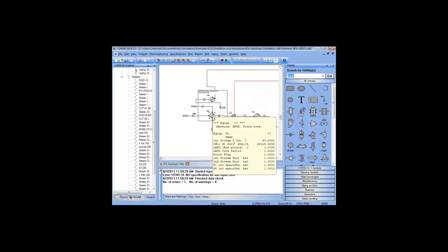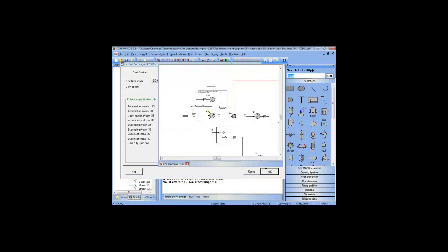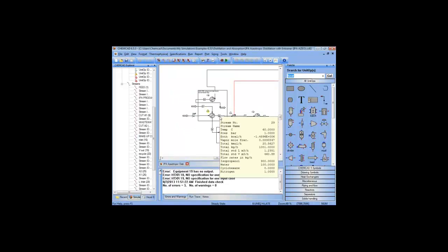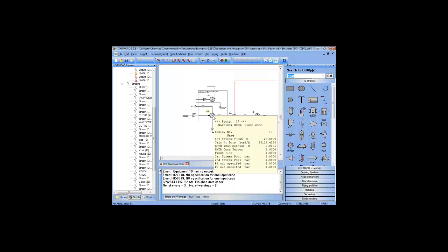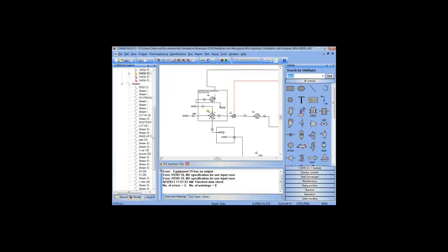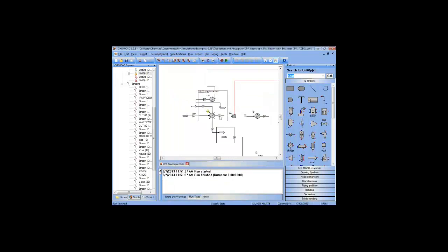And then I can just make adjustments and say, okay, maybe I can raise the temperature to 25 degrees. Do I have enough heat to do that? Right, so I'm still, well, I don't think I actually ran the simulation. Okay, so 25, I'm still getting the warning that one of my flows is too small, so I just wasn't recirculating much. I can play games until I find something here that will give me a good answer, and then I'll connect the streams. Why am I so cautious with this?